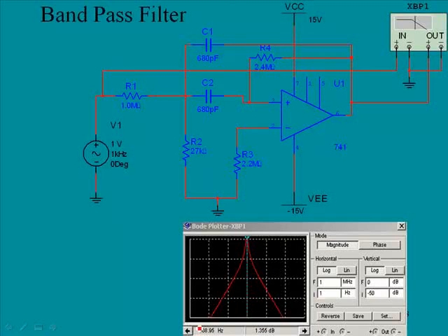And you'll notice down here it's 968.9, it's about 969 hertz, that is the passing frequency. And what was our calculated value? It was 973. Okay, so that is really quite close to the actual value that we see in simulation.